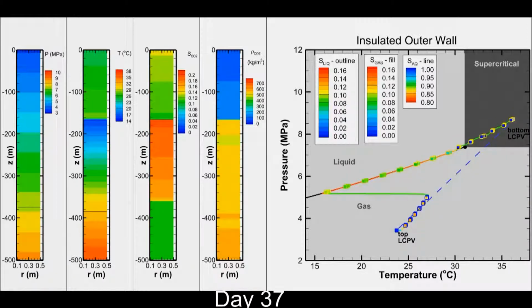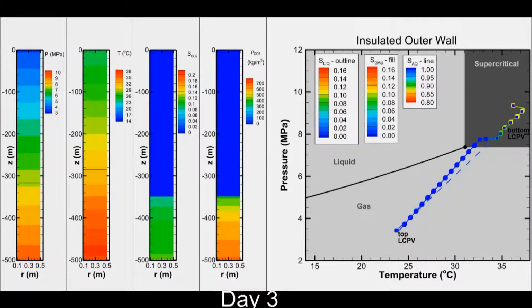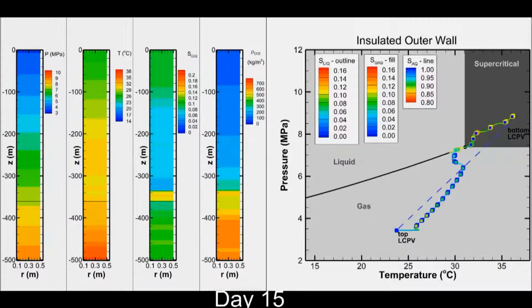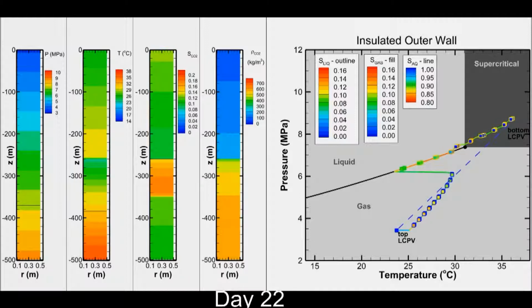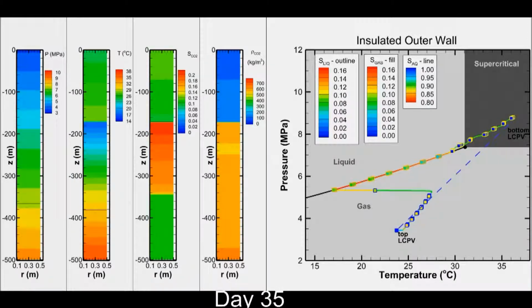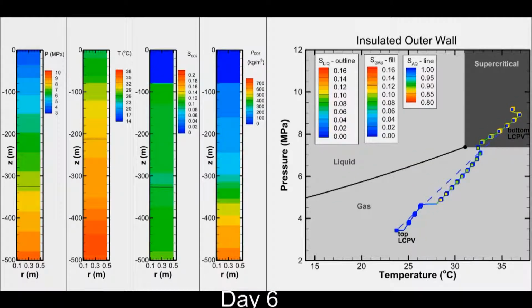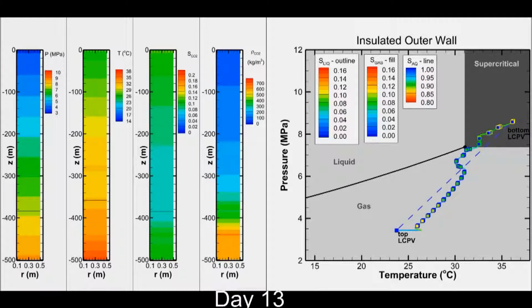The cooling continues as the system is stuck on the phase boundary, consistent with Gibbs' phase rule, until one of the phases disappears, which does not happen here before the system reaches temperatures that are out of range of Tough2 ECO2M. The significance of this simulation is the formation of liquid CO2. This occurs because of decompression cooling.